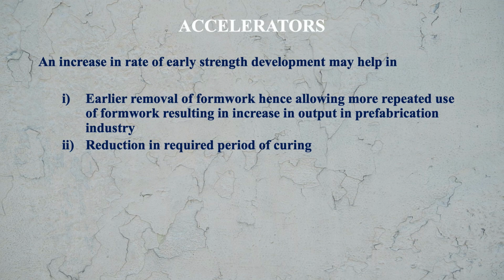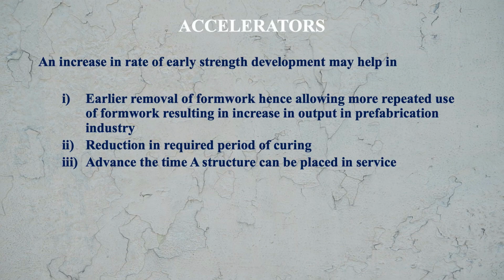Another way is reduction in required period of curing. Because if we get the early strength, then we can reduce the curing period. Advance the time a structure can be placed in service. If we get the early strength of the concrete, then the structure can be placed in service at an early stage.